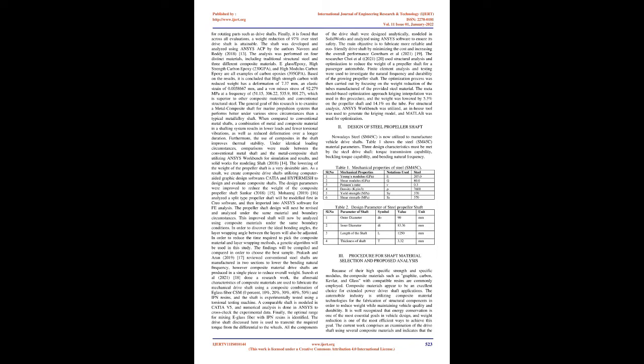Rao, 2016. High-strength carbon composite drive shafts have been created in this effort to replace an automobile steel drive shaft. Using FEA, an attempt was made to determine deflection, stresses under applied loads, and natural frequencies. When compared to a traditional steel drive shaft, the use of composite materials resulted in significant weight savings ranging from 70% to 63%. Finally, the author compared boron to HS carbon/epoxy; the cost of composite material is low and best. Mohan and Vinod, 2016.